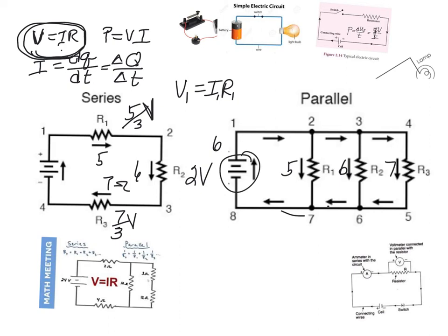So this is the whole lab problem of unscrewing the light bulb. If I unscrew resistor 3, it doesn't prevent current from going through here. Whereas if I unscrew resistor 3 over here, it's like opening the switch and stops the current. And you'll see this situation when you do the lab, which will soon be posted.